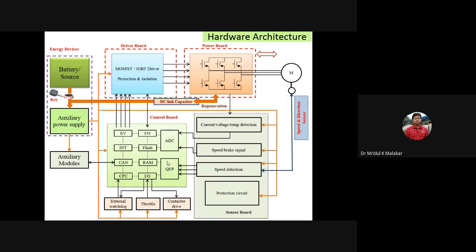So depending on the system requirement, you have to use your microcontroller. Basically it is a low power system. This low power system requires a gate driver which will drive the IGBTs or MOSFETs at the desired 15 volt or 12 volt, or 1 ampere maximum. It converts the PWM control pulses you are giving into the desired value for the MOSFET and driver.